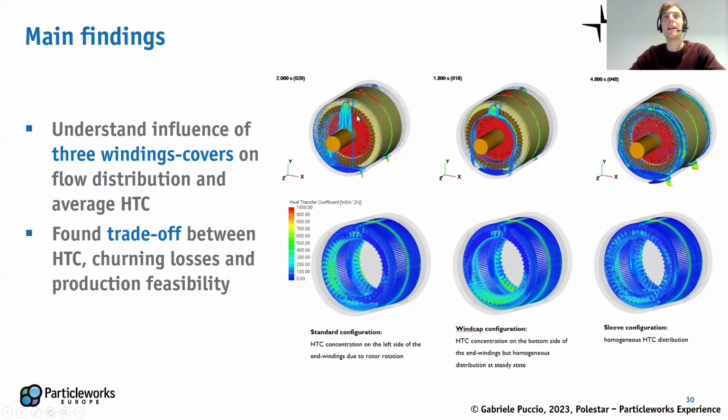The purpose was exactly that: to test, in less than 1 week, several geometrical modifications of this baffle to change and optimize the flow of oil inside the e-motor. A trade-off was found between cooling capabilities and churning losses due to oil entering the air gap.